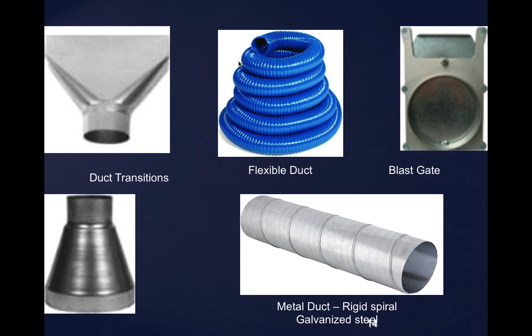But cooling towers, the way that they work is that you suck air in from the sides and you discharge air out the top. And that air is being blown against a spray of water because you want to cool that water by evaporation. So you want a fine spray of water and you want a lot of air so you maximize the surface contact between them and you cool that water so you can use it to cool the air conditioning system. Right? So what happens is you're sucking in air alongside of these towers. If you have a smokestack nearby, even if you're meeting the rules, 10 feet above and so on and so forth, and within 50 feet, you can get a downdraft. You can get a lot of this stuff sucked back down.